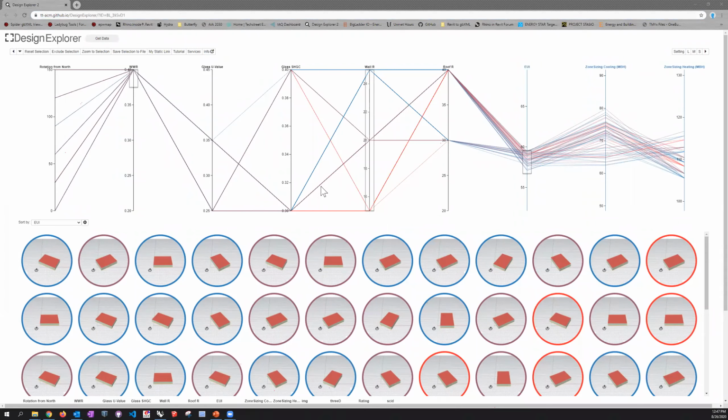So yeah, that's pretty much it as far as the workflow. Just use Honeybee to create your energy model, run that energy model hundreds of times, then use Design Explorer to visualize those results to try to help make design decisions. And you can get as crazy as you want with inputs and outputs. You could try to incorporate some sort of cost component as an output, where it's going to cost so much more for your insulation or to upgrade the glazing, and see how that works, and maybe even do a cost for the energy. So you can kind of get a feel for how that works.